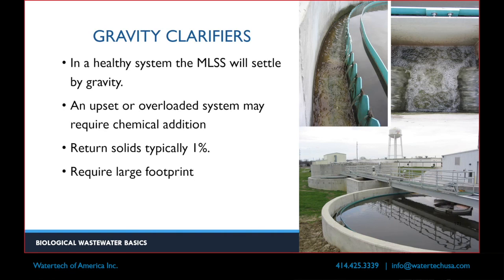Then you have to take the solids off the bottom and return them into the process. They're typically around 1% solids towards the bottom of the clarifier. Again, you can tell, big footprint. So this is 1 million gallons, 1.2 million gallons a day. They take up lots of space. This place had a ton of space. Some places do not.